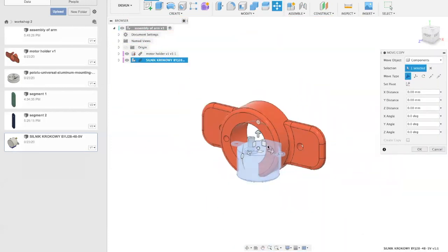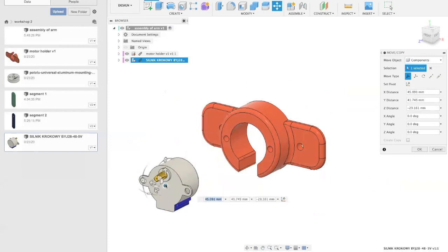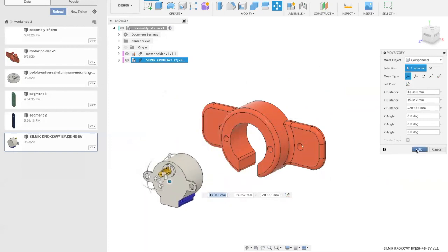This one also came in a bit crooked, so I'm going to rotate it facing this way. Make sure it's a multiple of 90, so negative 180 is, and then I'm going to rotate it upwards 90 degrees. You can also change these manually over here. And lastly, this center dot is how you will move it, like translate it around. So you just want to move it outside for easy access and then press OK.